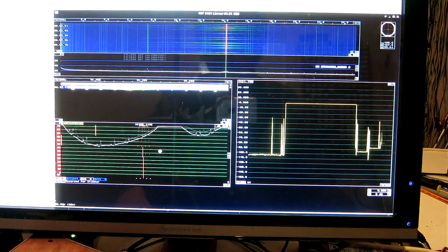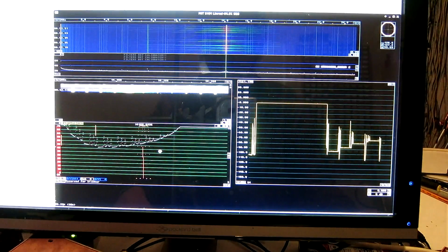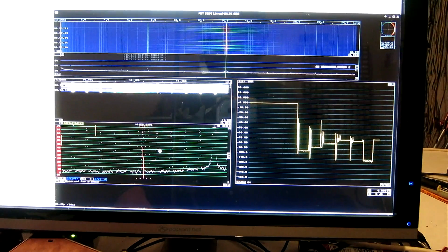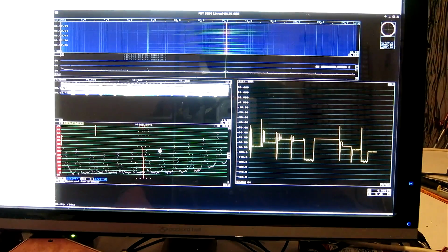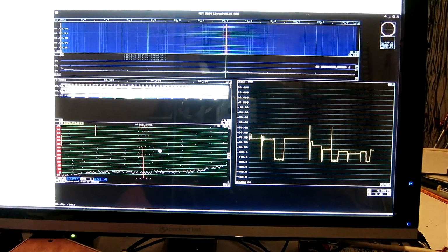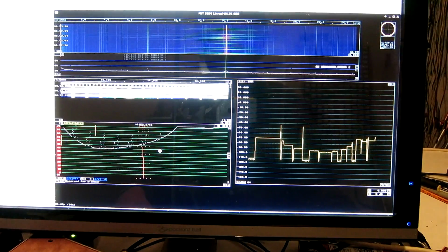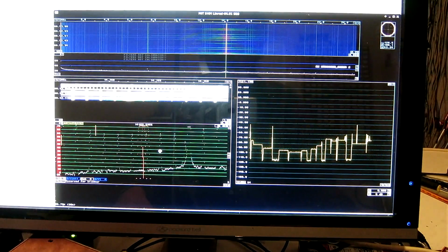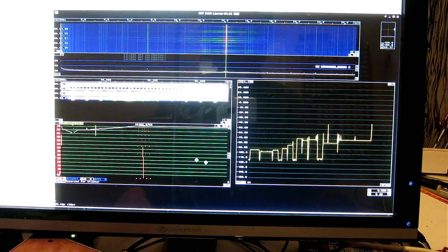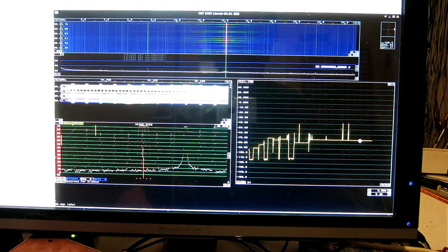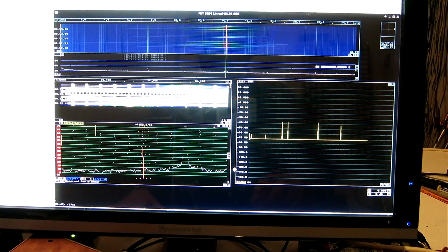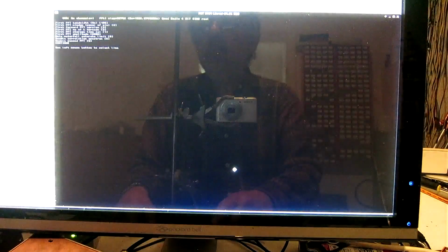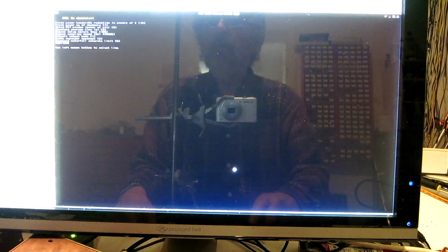And you can see when the strong signal is moved further away, they become stronger. And then they go down again. So it's a peculiarity. The strongest are in the order of 72 dB. So I need to make the bandwidth reduction bigger. I'll go for 9 here.